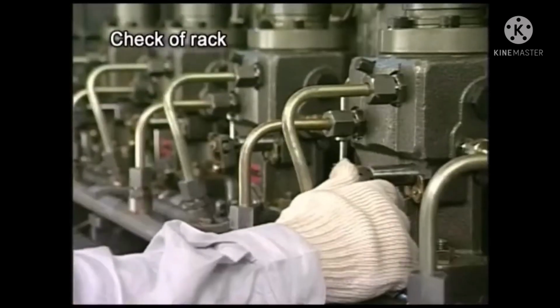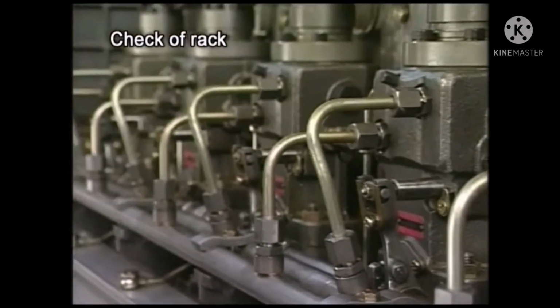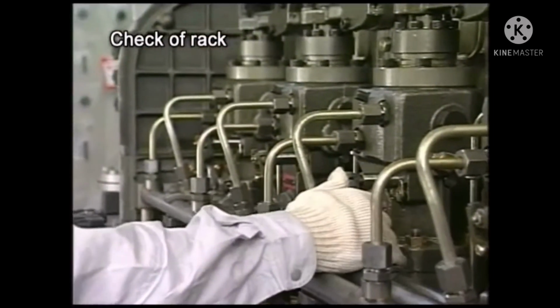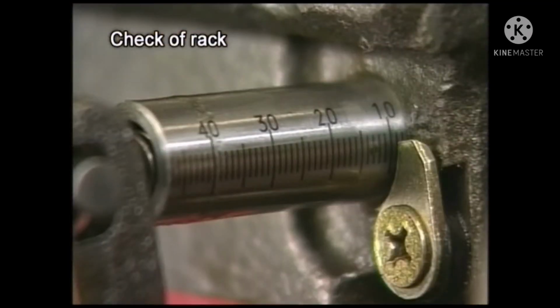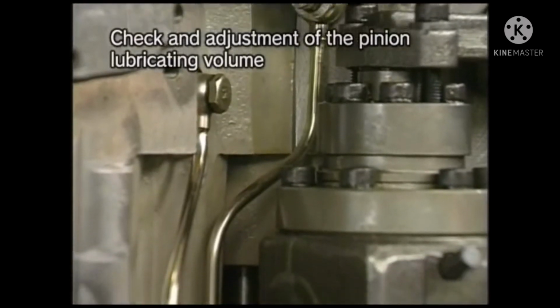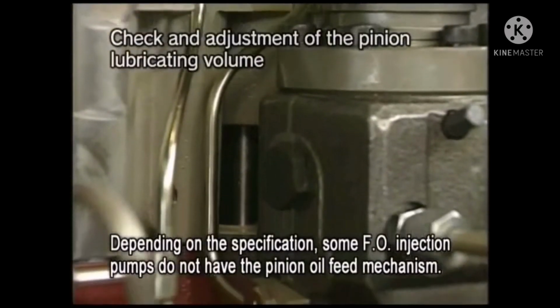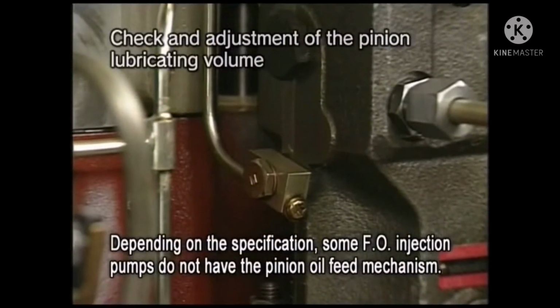First, remove the pump cover to check that the rack has not gotten stuck. Also, check the position to see if the graduation doesn't vary widely between cylinders. For HFO specifications, lube oil is fed into the pinion sleeve of the fuel injection pump. So check about it.